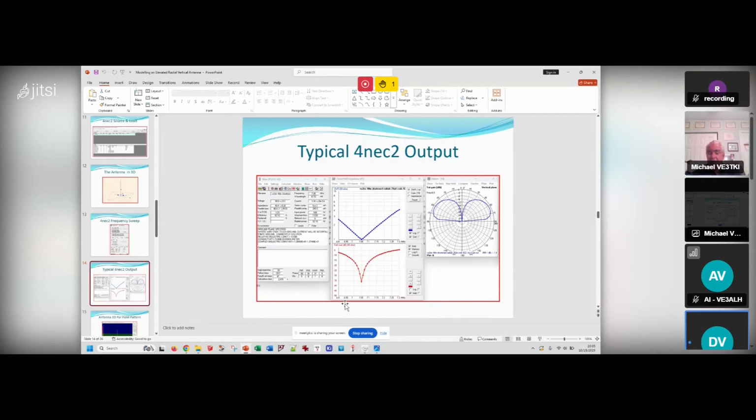As I recall, Dave had spirally wound the antenna itself around a set of the 2-inch fiberglass masts that people were buying at Princess Auto years ago. Anyways, he spirally wound it around that, and that might be a way to get 80 meters onto the size of your, I don't know if your spider pole would take that, but it'd have to be small wire. That's the other thing.